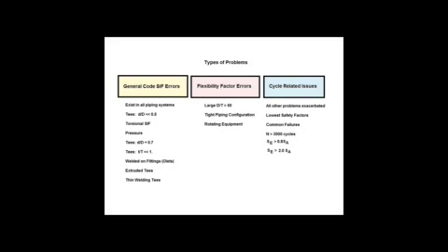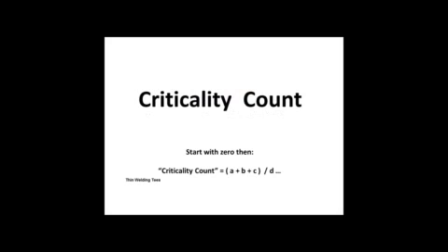We also know that for cyclic services, the safety factors we deal with drop down to a fixed value at about 3,000 cycles. So once we hit 3,000 cycles and have relatively high stresses, we need to be extra careful. And that's a time when a tool like FEA tools can be used more readily.